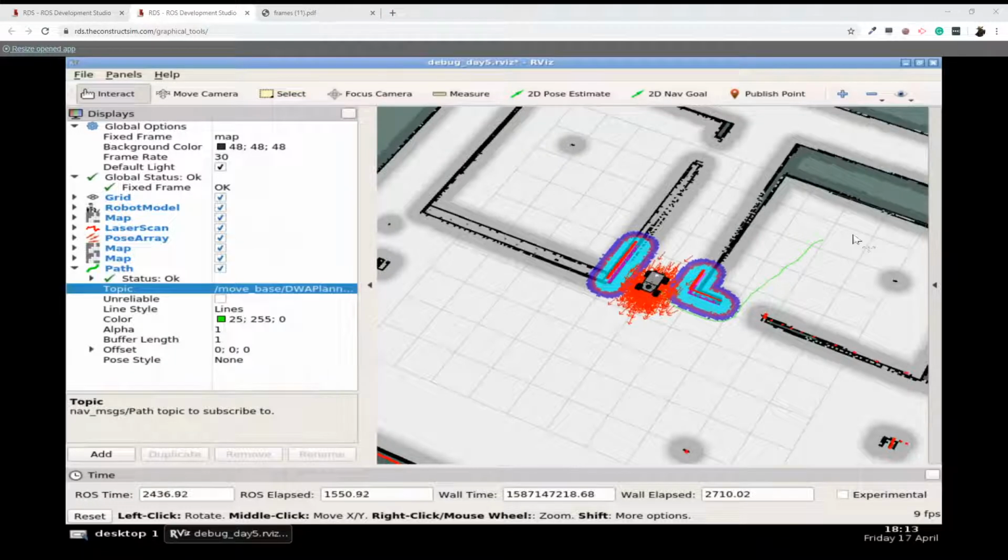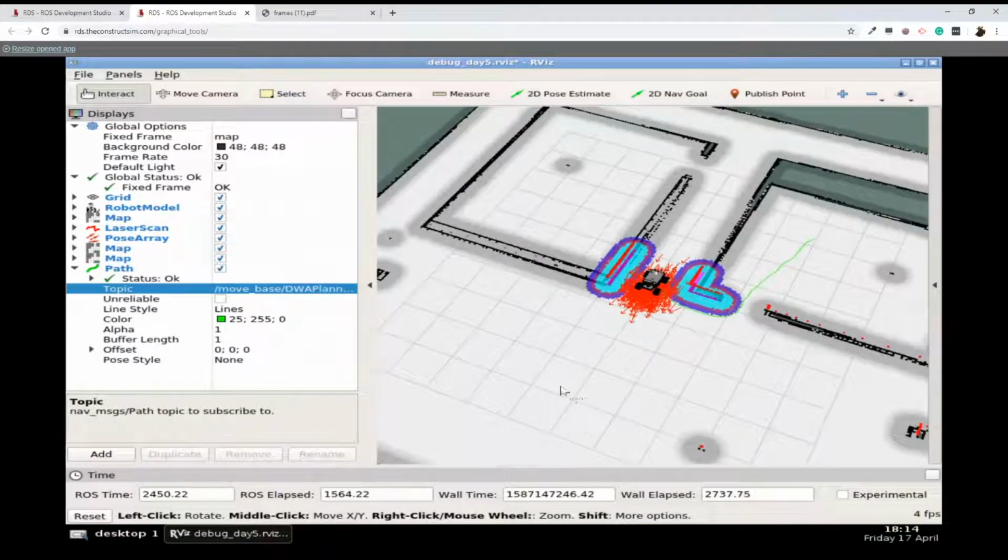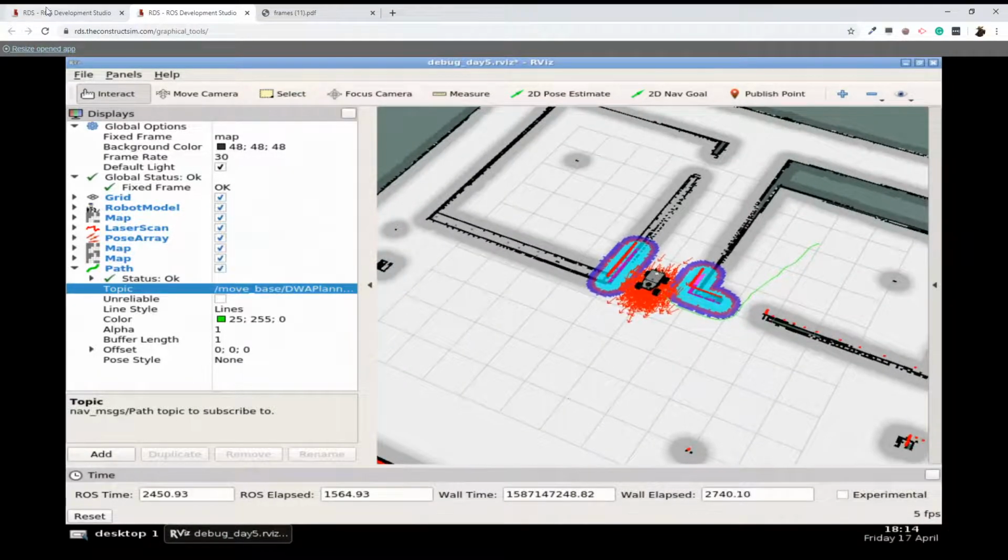Okay, thank you. Sensor messages, laser scan. What is the ray trace? I can see here the construct has already answered to you. Yeah, that's it. So if you can set the range to 3 meters, then anything which is farther away than 3 meters from the robot is going to be just ignored. Yes.